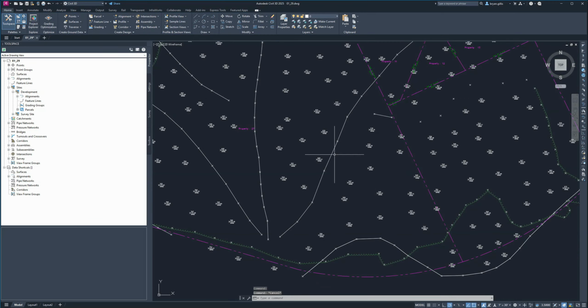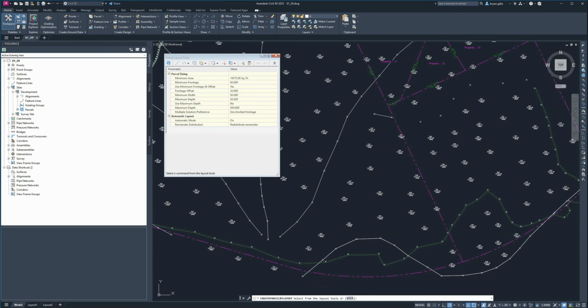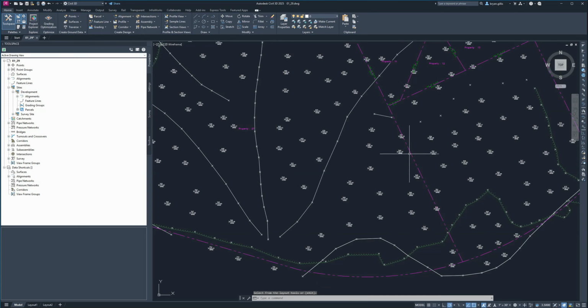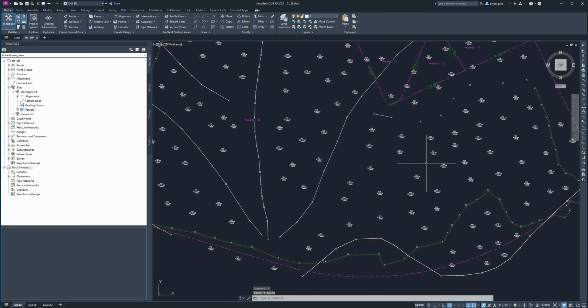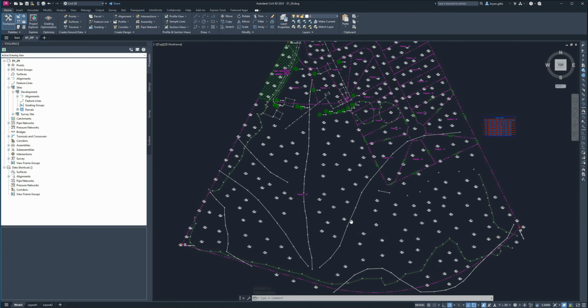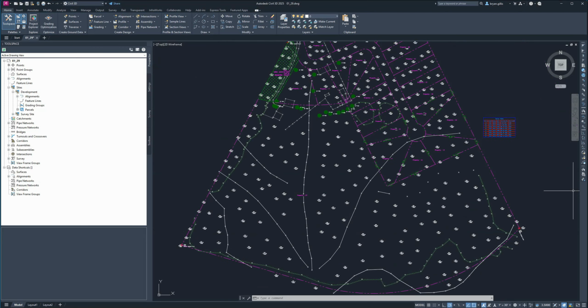If we go back into our parcel creation tools, we can just select this, type E for our erase command, and press enter, and it'll pull that segment out for you right away. So we saw a few different ways to delete parcels and parcel segments. One, if we do unions of multiple parcels, no longer relevant boundary pieces can simply be erased. Parcels that we created from objects, like our box in the beginning, can be deleted just with the erase command.